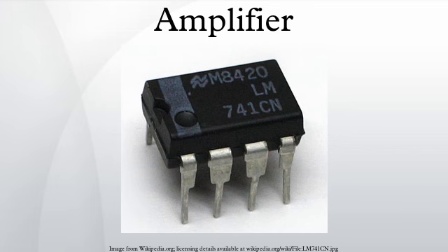The common emitter is most often configured to provide amplification of a voltage applied between base and emitter, and the output signal taken between collector and emitter will be inverted, relative to the input. The common collector arrangement applies the input voltage between base and collector, and takes the output voltage between emitter and collector. This results in negative feedback, and the output voltage will tend to follow the input voltage. The common collector circuit is therefore better known as an emitter follower, source follower, or cathode follower.